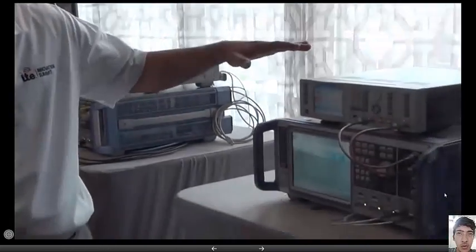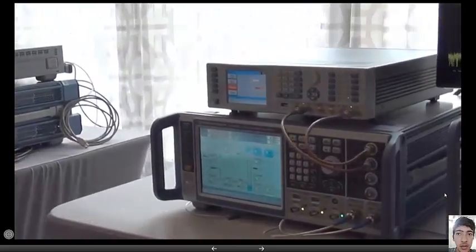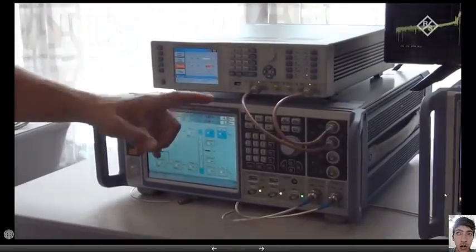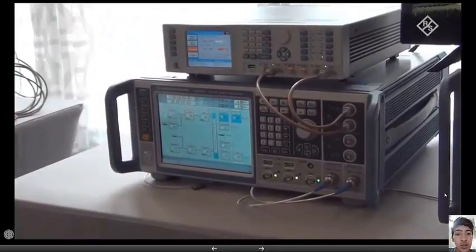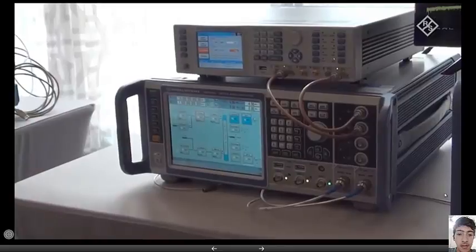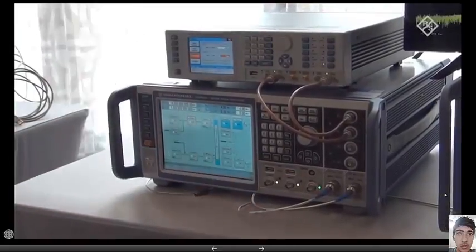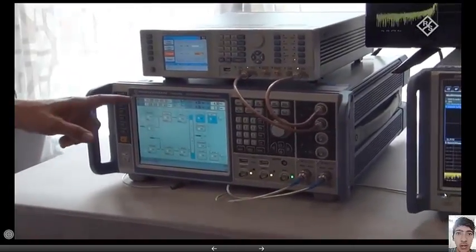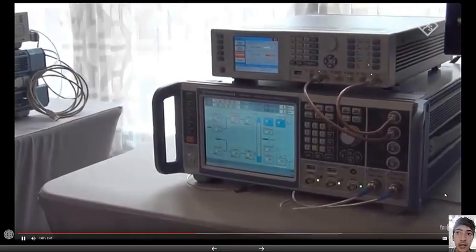And then, of course, as a test equipment vendor, we have to provide solutions to analyze such ultra-wideband signals and to generate them. So this is basically the setup that we have here to do that. We're utilizing a wideband arbitrary waveform generator that we connect over analog IQ to our vector signal generator, the SMW200A. Right now I'm using a 2-channel model where both channels go up to 20 gigahertz. The demonstration that we do here is right now at 18 gigahertz.